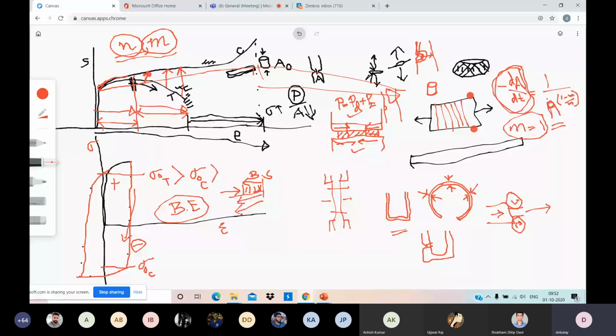Another reason I have told you is that strain hardening will also go down a bit, because of the dislocations you generated the first time. When you do reverse loading, in general, opposite kinds of dislocations will come and they may annihilate each other, cancel each other.